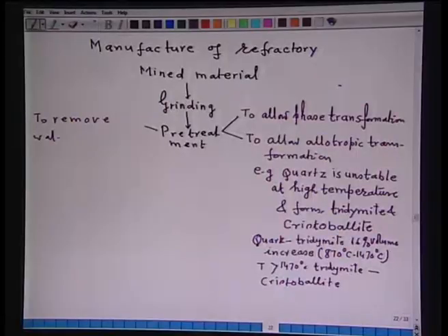Another important issue in case of pretreatment is to remove water of hydration. For example, fireclay occurs in nature, and the water is in combined form; also free water is there. So, this water of hydration has to be eliminated, so that at the time of its application, when water evolves, it will not create a lot of problems.